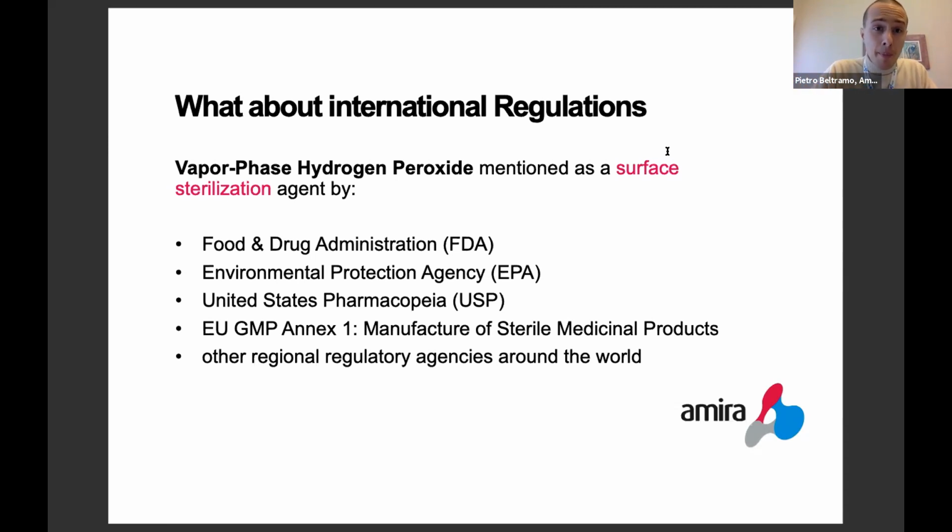There are applications where the temperature must be very low. One typical example is food. Whenever you need to treat food decontamination, usually they work in atmospheres that are 4 or 5 degrees C, very, very cold. No way to apply the VHP because the gas will condense into liquid immediately. It's too cold, you know. You generate the gas and the gas, boom, liquid. So for those conditions, it's very good to work with spray application because there will not be a problem. It's liquid already. It's not depending on the temperature anymore.